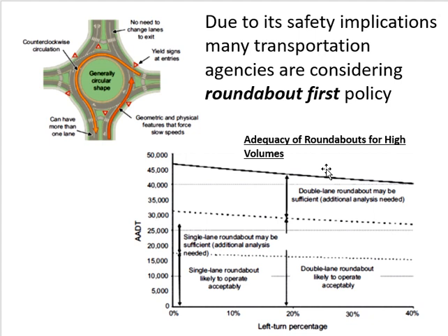So average annual daily traffic is the average traffic of the whole day from all directions. You put it on the y-axis. Then on the x-axis, from the AADT, what percentage is left turning. So again, left turning from north side, south side, east side, west side, and you add these percentages together, and then you put it on the x-axis.